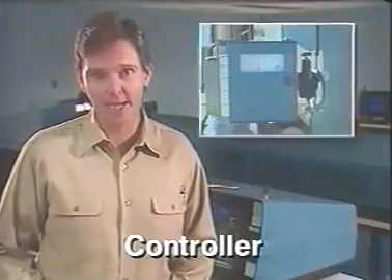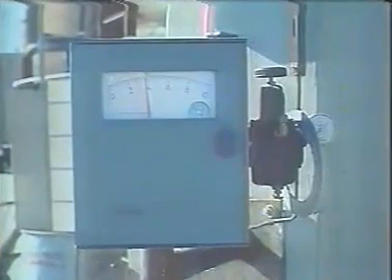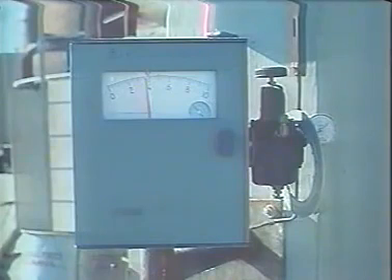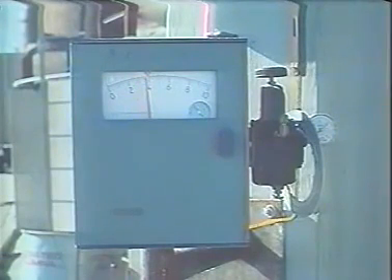Controllers are the next group of instruments. Controllers tell valves what action to take. A control mechanism inside a controller receives the measurement signals from a transmitter. After comparing the measurement with a desired value, the controller transmits a signal to a valve or other final control element. So, a controller consists of a comparing mechanism and a transmitter combined in the same housing.